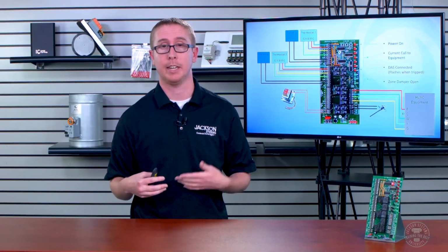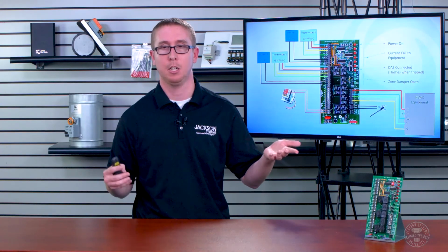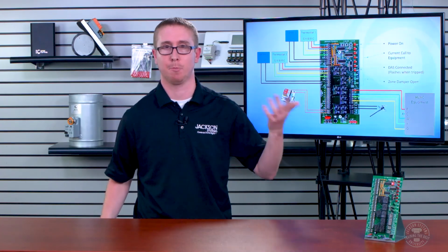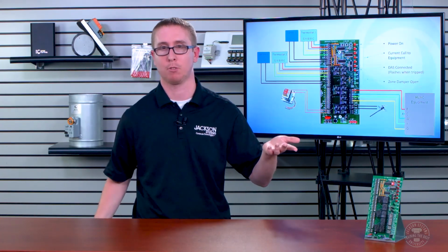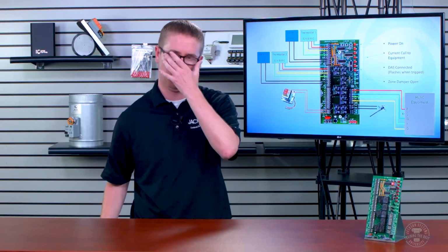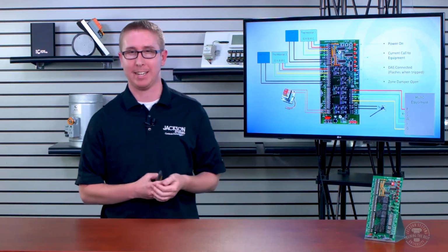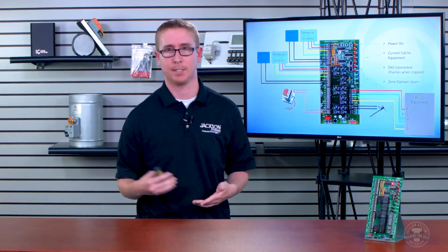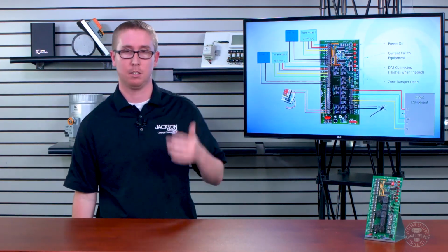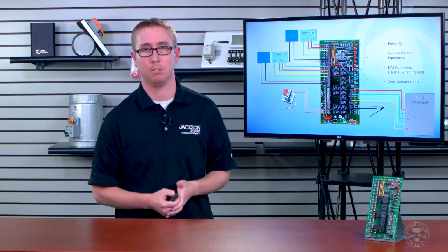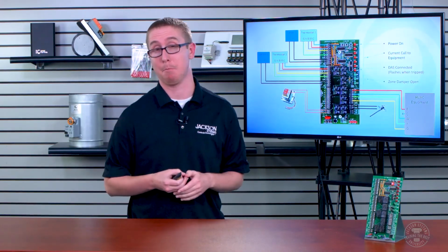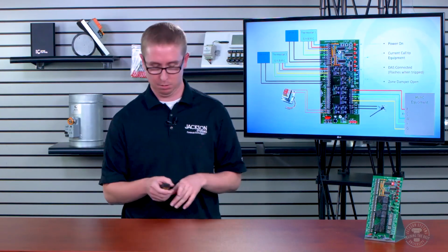And then obviously the zone thermostat could be calling, but the HVAC equipment could be running the opposite mode. So the thermostat could be calling for heating while the equipment's running cooling because a different zone is calling for cooling. So just note, I get a lot of calls from time to time saying zone 1's calling but its damper's not open. I look at the zone panel, zone 1 LED isn't on, and so it knows zone 1 damper isn't open, and there's a reason for that.